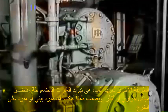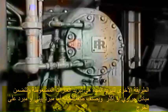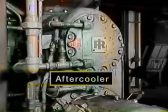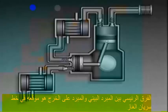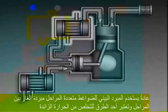The other method of water cooling cools just the compressed gas. This method involves one or more shell and tube heat exchangers. Depending on their location, these heat exchangers are classified as either intercoolers or aftercoolers. The main difference between intercoolers and aftercoolers is where they're located in the flow path of the compressed gas. Intercoolers are generally used with multi-stage compressors and are located between the stages.